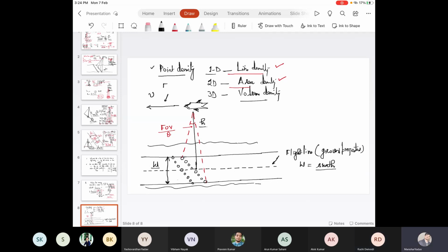Listen carefully. The width, this swath, I have defined by this line perpendicular to the boundary of the area strip. While this is a slant line, these laser footprints are hitting the ground along a particular line. It is called a scan line. But why is this scan line slant? Why is it not perpendicular to the boundary of this area strip?